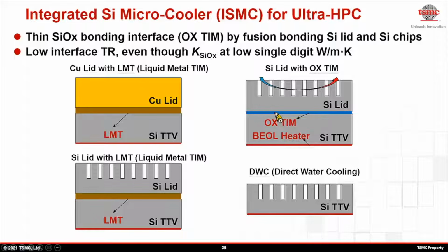And we even evaluate the case that we eliminate the bonded silicon lid and put silicon microcooler located at the back of the SoC, allowing liquid coolant approach even closer to the heat source to hopefully better remove the heat efficiently and effectively.